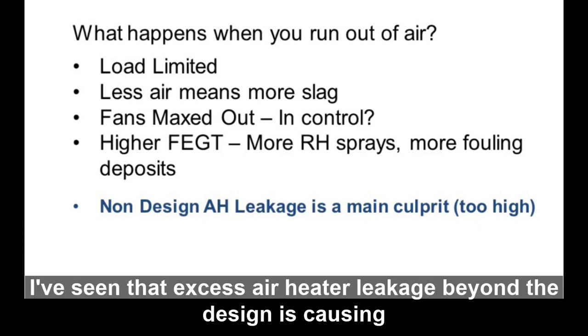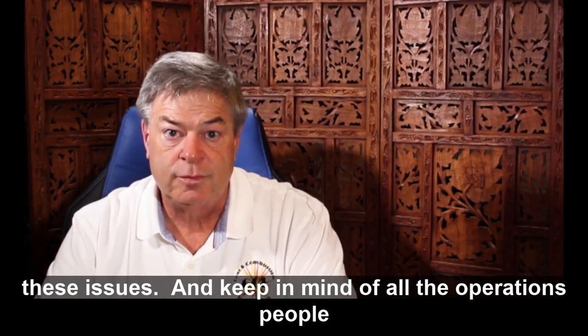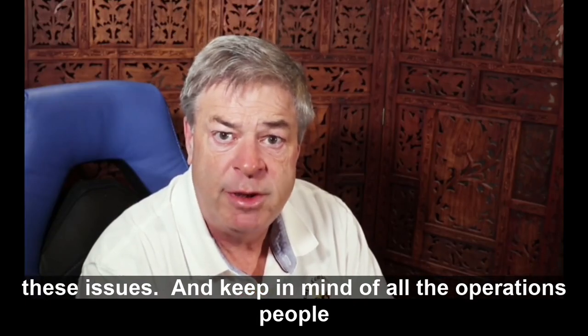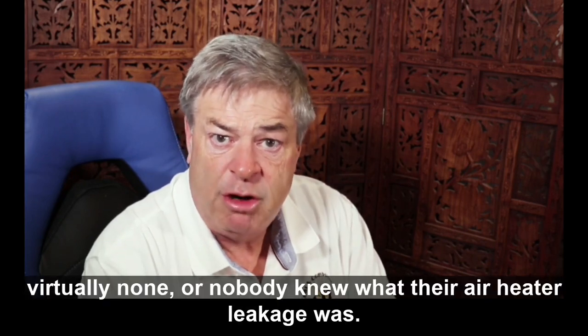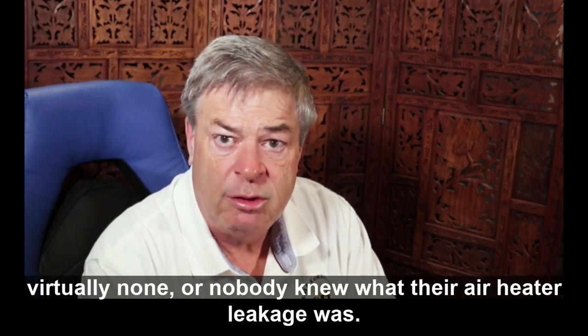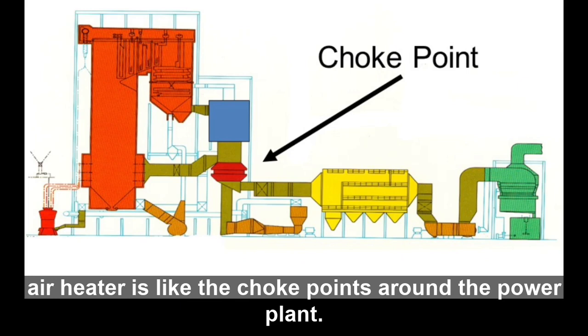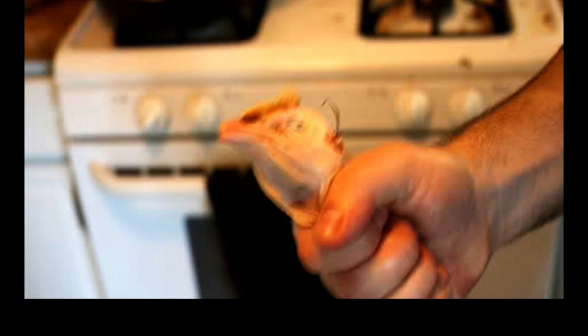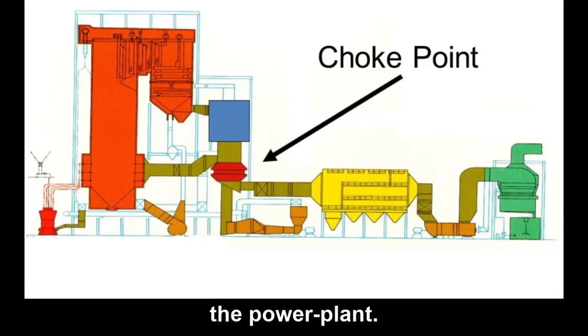And in numerous cases, I've seen that excess air heater leakage beyond the design is causing these issues. And keep in mind, of all the operations people I've talked to or taught classes to, virtually nobody knew what their air heater leakage was. I sometimes joke, just so you can remember how important this is, that the air heater and air heater leakage is like the choke point around a power plant.